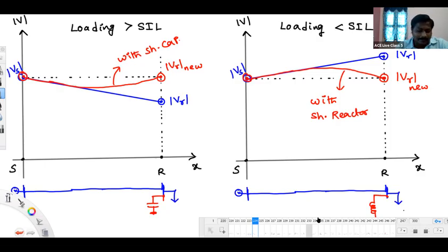See, maintaining a number of capacitor banks is not that easy on the transmission line. Particularly for series capacitors, you have to install a separate station at each and every place on the line. It may come in future, definitely. Already we have some series capacitor stations by means of FACTS controllers, practically on 400 kV lines and 765 kV lines. But providing distributed compensation has not yet come into practice. Thank you.